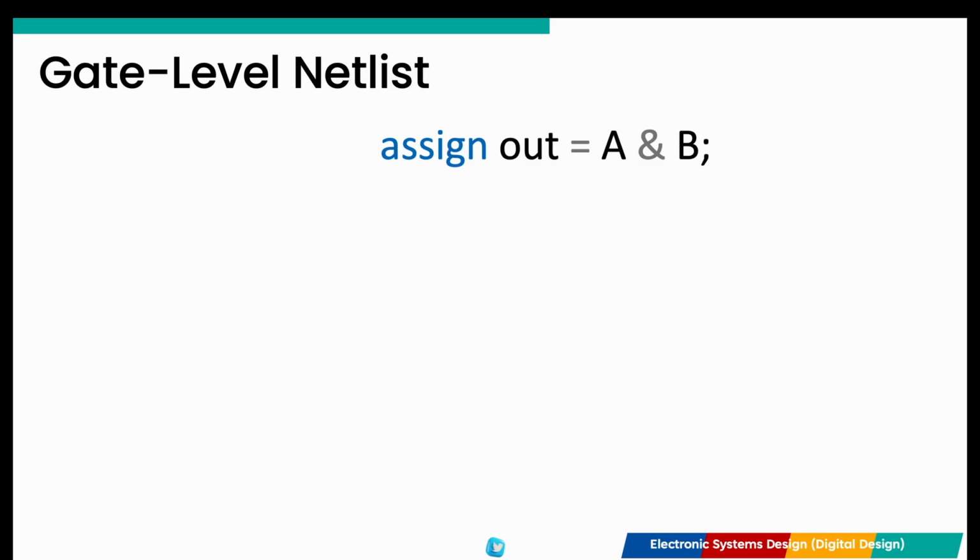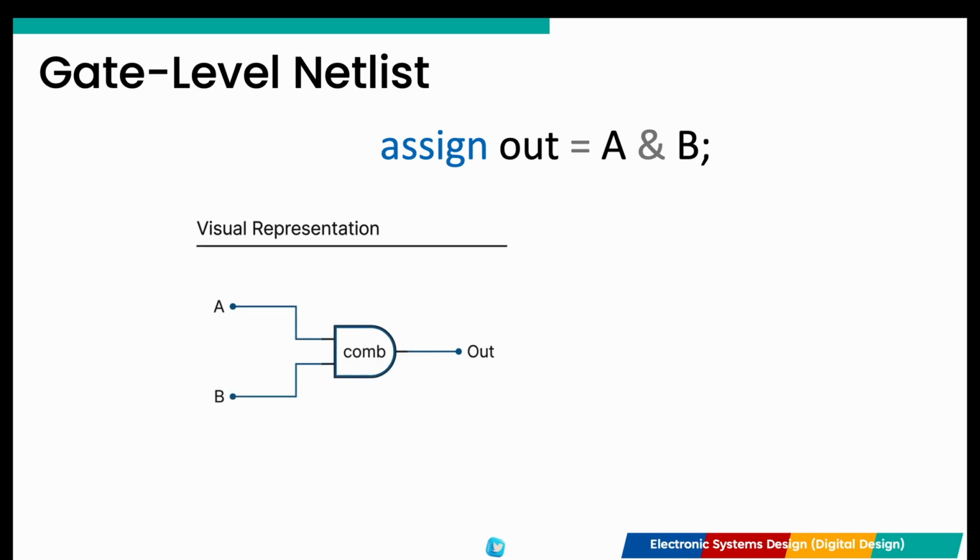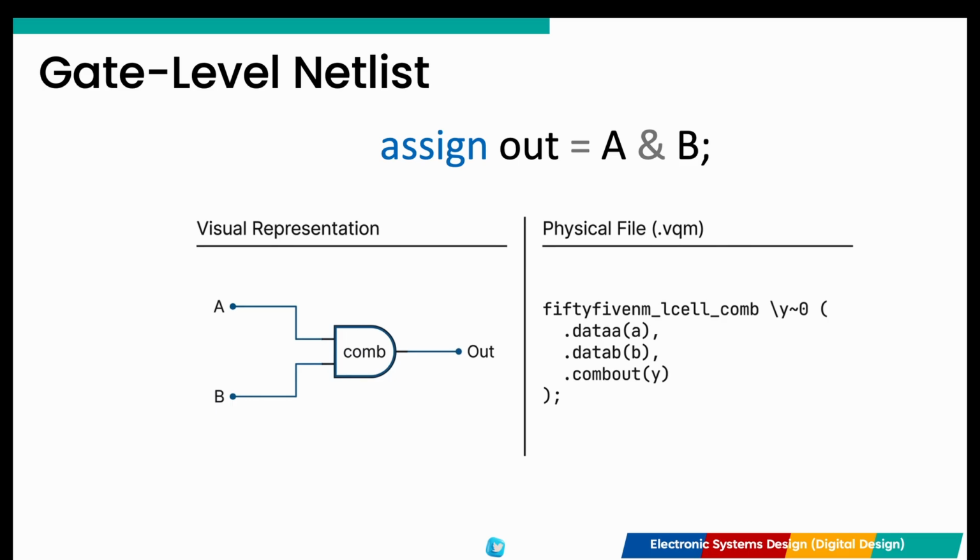This is a structural Verilog that represents your design using actual primitives or building blocks of the specific FPGA you chose. At this point, your hardware-level case statements and if-else blocks are gone. They have been replaced by a massive list of wires and specific hardware instances. This netlist is the master blueprint that the Place and Route tool will use to decide exactly where to put each component on this silicon fabric.